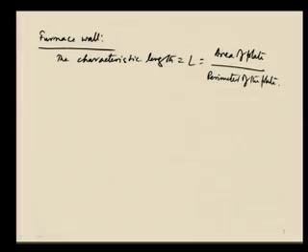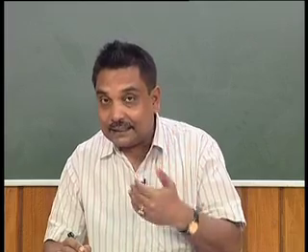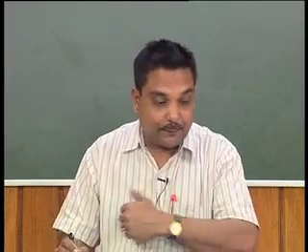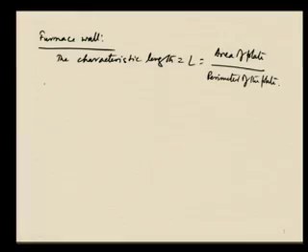Now, what we have discussed so far are vertical plate conditions, and these can also be used for inclined conditions, as well as for vertical tubes, where certain conditions apply so that vertical tubes can be viewed as a vertical plate. Now, the second part is heat transfer at constant heat flux condition.